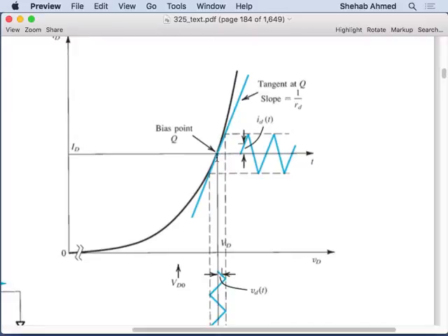And then we will do an AC analysis, AC small signal analysis, with a physical limit on the signal based on the physics of the device as well. Just that the device physics is different. Here, it's V over VT that we limit to less than 1. In the MOSFET, it will be something else. In the BJT, it will be something else. But it's the same. And all of them, what did they do? They amplified the current or amplified the quantity.